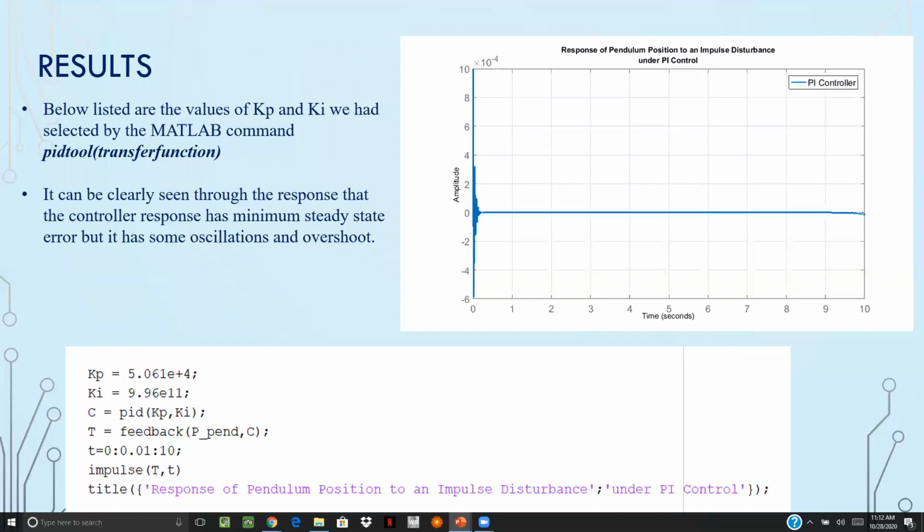When talking to our group members and observing our analysis, it can be clearly observed from the output performance result that the controller is tracking its reference nicely, but at the expense of overshoots and undershoots. And we think that it can still be enhanced by adding a derivative part, and then hopefully we can reduce some overshoots and undershoots.